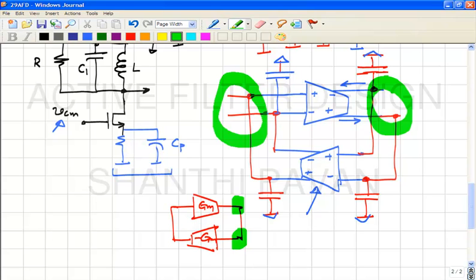Okay? And these transconductors have been connected in this particular fashion because we are trying to realize a gyrator, and as far as we are concerned, we only really care about the differential signals, correct? As long as the common mode voltage is held at VCM ref, we are not attempting to do anything with the common mode feedback loop.